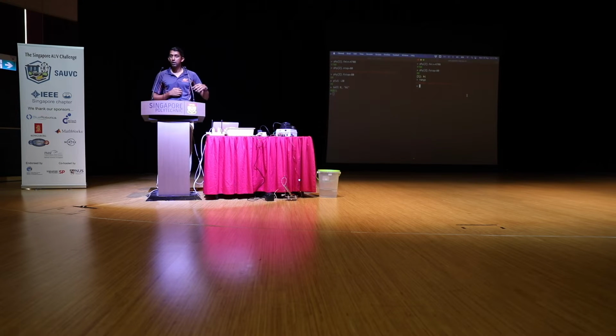So earlier I talked about how I have 2 Raspberry Pis on my table. What I have on the screen is that I have connected to the transmitting Raspberry Pi on the left, and the receiving Raspberry Pi on the right. And you can see that there are 2 things that I set. Again, without going into a lot more detail, when you use your laptop and download the system, when you're transmitting, it is using a speaker band from 9 kilohertz to 15 kilohertz. That's why it's a high pitch sound. But the underwater speaker that I'm using does not respond to that high frequency sound. It is actually a slightly lower frequency band. So I have to set the starting frequency to 4.7 kilohertz.